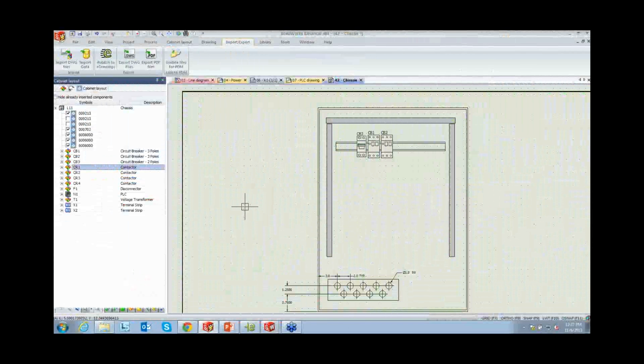So wire numbering information along with length is, I know, very important to a few of our clients, which they provide to their manufacturing floor, and even for on-field installation, because it's so much easier to look at a report going, okay, I need to connect wire 1 to here, this is the length I need to cut it with, and that just makes it easier. It's a time saver. It saves you on production costs, especially if you're building cables in bulk. It makes a big difference.